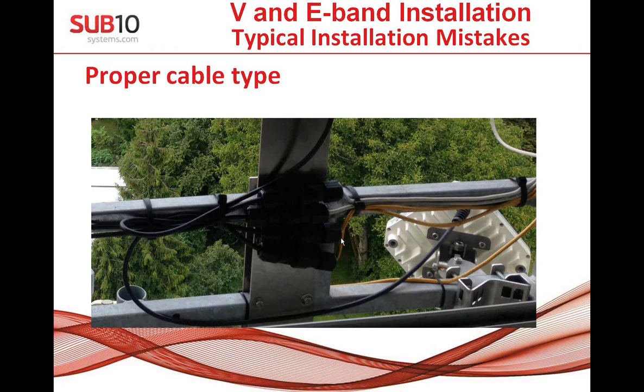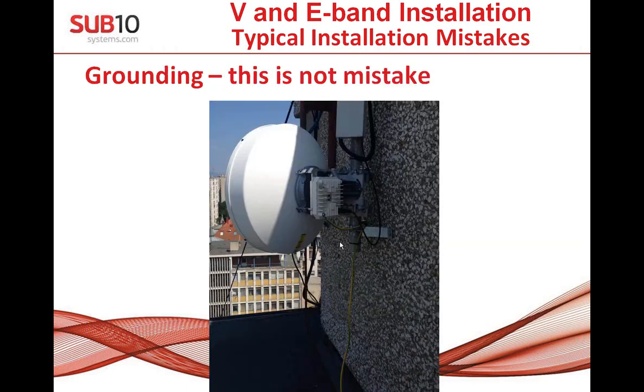It was obvious that for gigabit Ethernet, all 8 wires have to be okay. For fast Ethernet, just 4 wires are enough. And it was exactly the case that the brown wire was affected, and it was making a loop between the ground and this wire. Next example is good.